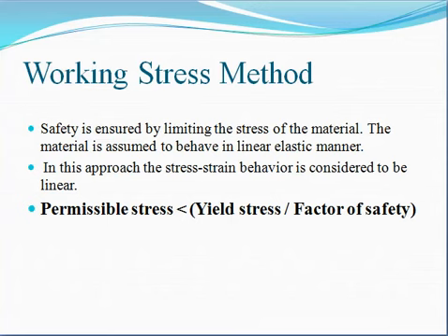It is one of the oldest methods of design, suitable for all structures. Though IS 800-2007 insists on limit state design, it permits the use of this method wherever LSM, that is limit state method, cannot be conveniently adopted. An example is a water tank. In the design of a water tank, we cannot use the limit state method. For the design of a water tank, we have to use this working stress method.